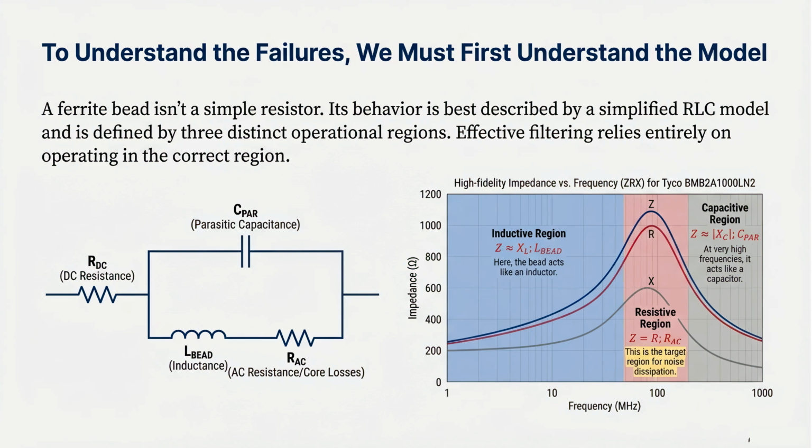Its behavior is defined by three regions: inductive, resistive, and capacitive. Effective filtering relies on operating within the resistive region for noise dissipation.